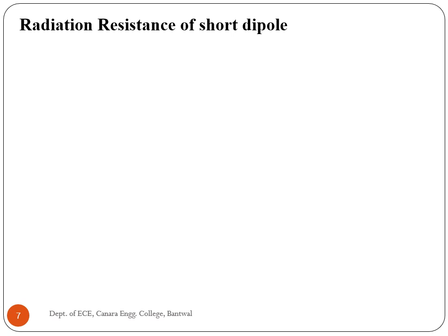We know that the short dipole consists of a thin conductor of length L with a uniform current I and point charges Q at both ends. Then the average Poynting vector is given by S equal to half real part of E cross H conjugate, electric field and magnetic field. The far field components are E theta and H phi, where E r is negligible.